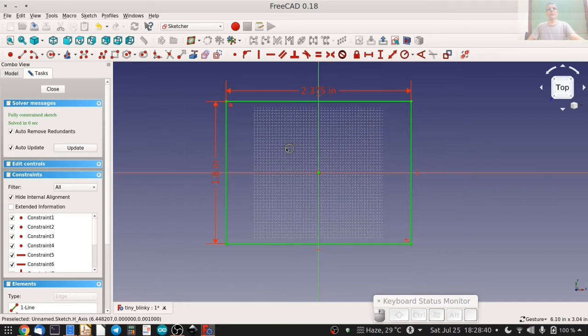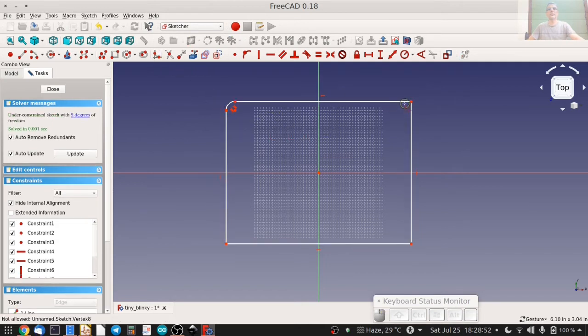But let's say we want to have a more complex sketch to start with. We want to include the fillets over here. Choose the fillet tool, click on one line and click on the other. That creates the fillet, and keep doing this for all of the corners where you want the fillets. That's the third corner, and that's the fourth corner. Press escape to get out of the fillet mode.